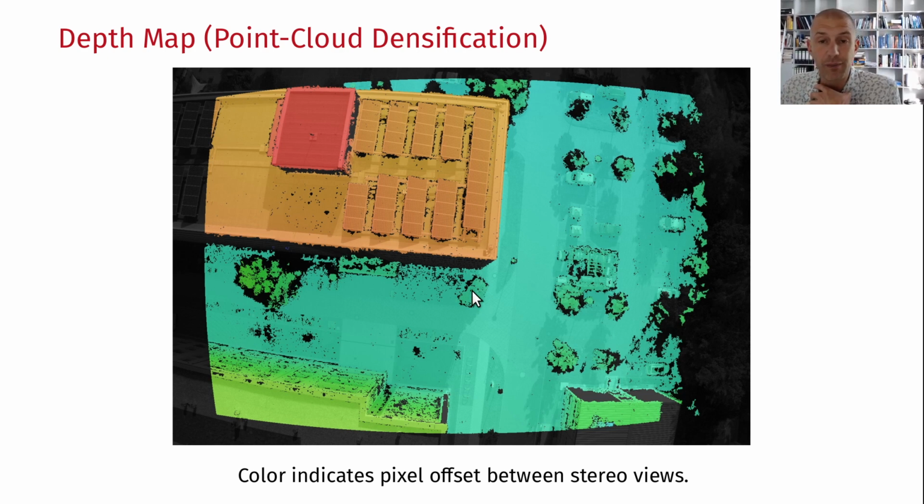And then each of these depth maps is transformed into a point cloud. Each of those depth maps has X, Y, Z coordinates, so if you have one depth map, you automatically have a point cloud. And you end up getting a very dense point cloud because you not only have one depth map, but several depth maps that end up being overlain. Sometimes, if you have worked with structure from motion point clouds, you realize that there's a little bit of noise above and below a surface. This, for example, stems from a bad alignment between two images. You can sometimes have one or a couple of images that didn't get well aligned, and then you end up producing a much more noisy point cloud.